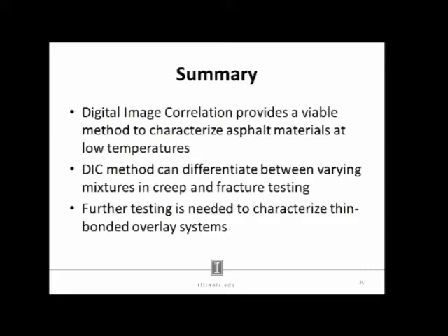And then obviously further testing is needed to characterize thin bonded overlay systems. That's going to be a little bit of a challenge dealing with a CT specimen. You have a smaller ligament length, and you're also dealing with a material that has even more heterogeneity within it from the location of the crack tip moving forward.